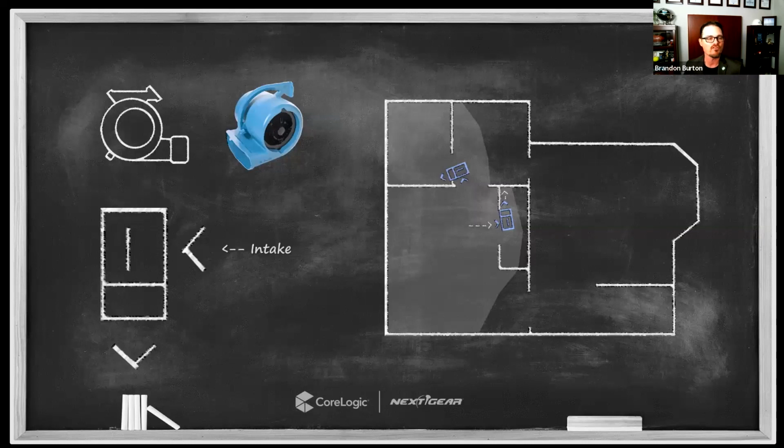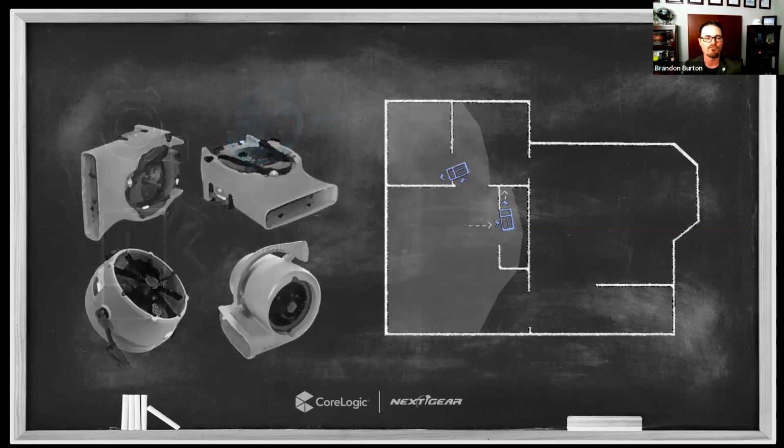Okay. Now, once these two air movers are installed, that was only 2 out of the 8 to 11 air movers we needed. Where do the rest of them go? Right. So the rest of them are going to continue that airflow around the perimeter of the room. And for this, I can use a number of different types. At the top of this image of air movers, you see the low profile type air movers.